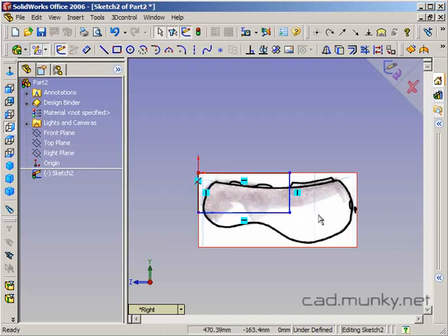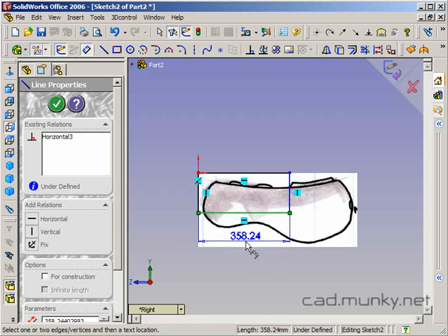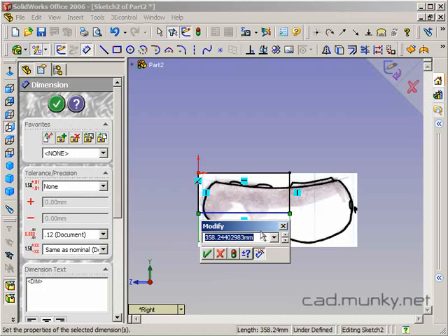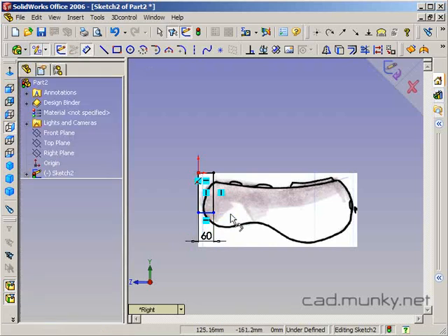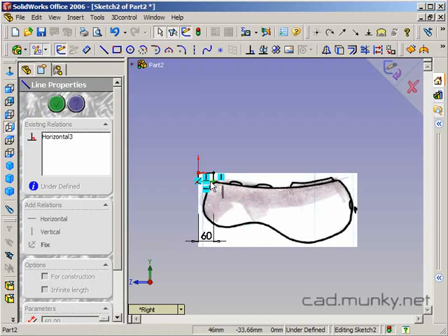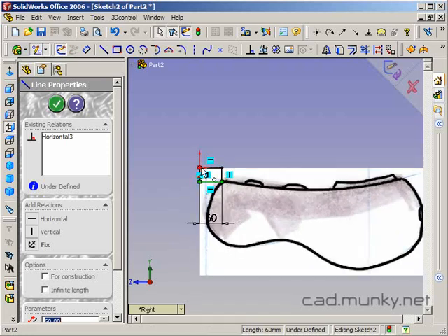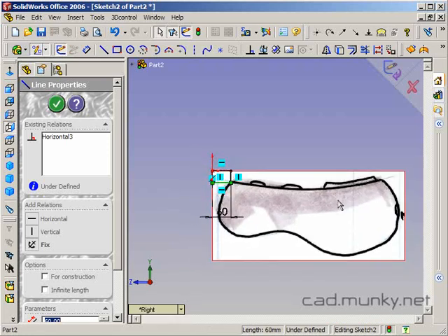And when I did this sketch, I figured that maybe the remote control was about 6 centimeters long total. So what I'm going to do is use my dimensioning tool to dimension this rectangle so that it's about that long. So 6 centimeters would be 60 millimeters. So obviously the rectangle is far too large at this point. So I'm just going to type in 60 here. And then clearly it's too tall, so I'm going to get out of my dimensioning tool and get about the aspect ratio that I want. So that's how big the side sketch should be, approximately.